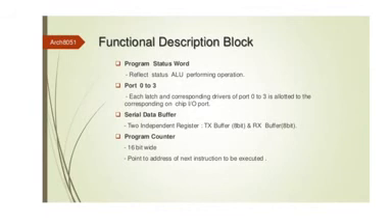This program status word, we'll actually know about in detail when we start the other slides. For now, I can say this is an 8-bit register, and it is also called the flag register, because it shows you the status of the operations after you get a result of addition, subtraction, multiplication, or some logical operation. If you get a result, whatever flag is high or low, that flag status it will be showing in this status word, the program status word.